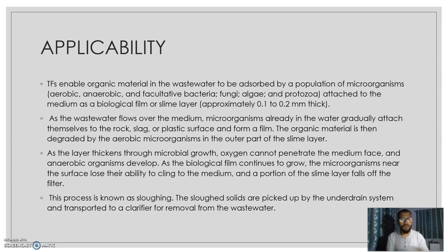Applicability. So the question arises where we can apply these trickling filters. Trickling filters enable organic material in wastewater to be absorbed by a population of microorganisms like aerobic, anaerobic, and facultative bacteria, fungi, algae, and protozoa attached to a medium as a biological film or a slime layer, approximately 0.1 to 0.2 mm thick. As the wastewater flows over the medium, microorganisms already in the water gradually attach themselves to the rock, slag, or plastic surface and form a film.